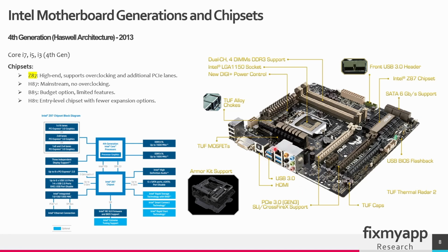Then we have the LAN connectivity, and according to the image, it will communicate to the chipset, so the data will go to the chipset and from there to the CPU. This is the audio part, and the audio part will communicate with the chipset. So it's the same story. The chipset defines how the communication goes, and if you're going to analyze the motherboard, it will help you to troubleshoot the problem. So if there are any audio problems, then you know, hey, this communicates with the chipset. I can investigate this part and maybe the chipset part, but the problem will not be the CPU.